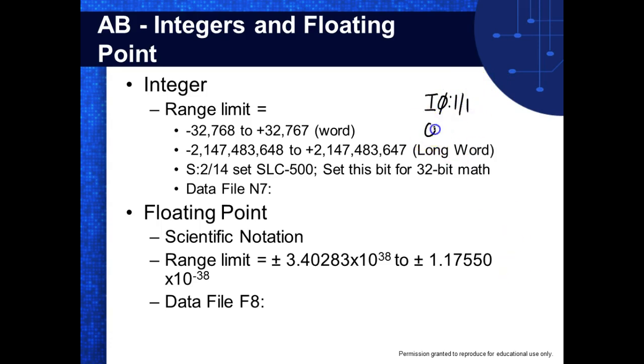And if I wanted an output, it's truly O, colon, 1/1. But we've only got one output register and one input register, so what does Allen Bradley not require you to use? You don't have to put the 1, because that's the only one you've got. It's not like B3 and B10, where to switch between those registers I have to specify another data file.